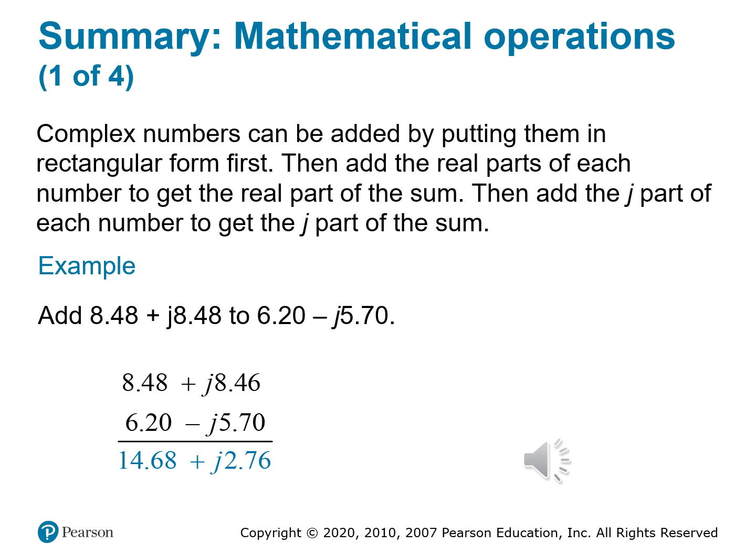And so this is just like adding phasors in a series RC or RL circuit where voltages or currents are out of phase. You align the real with real and the imaginary with imaginary. And when you're analyzing voltages across components like resistors and capacitors in AC circuits, phasors allow you to solve for net voltages or currents pretty quickly. But to do that, your phasors need to be in rectangular form so that you can easily add or subtract. You saw how easy that was, right? This mirrors what we did in the inductor model where we treated the real and the imaginary parts as legs of the impedance triangle. But here we're just adding those triangles in a flat rectangular space.